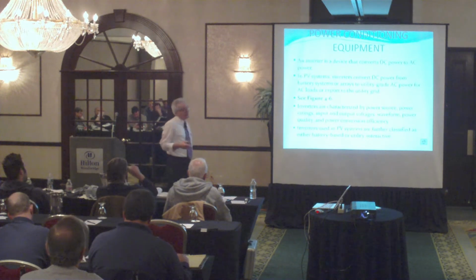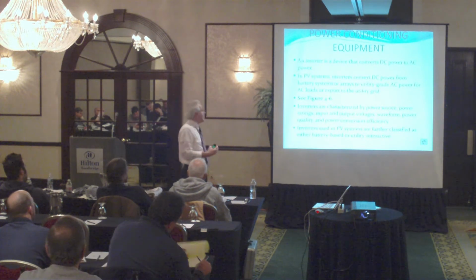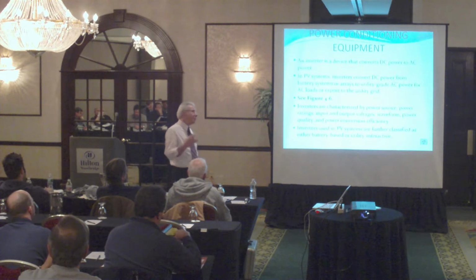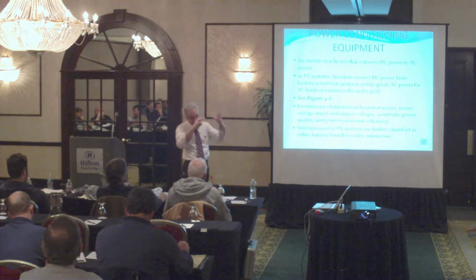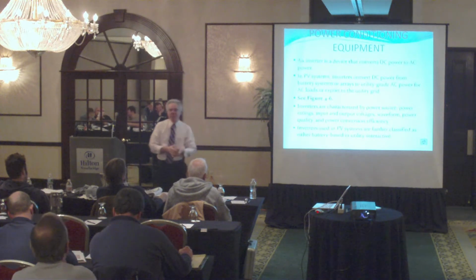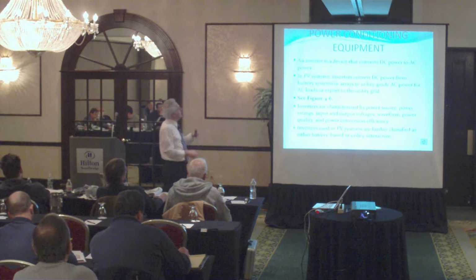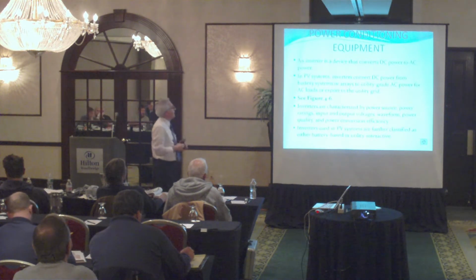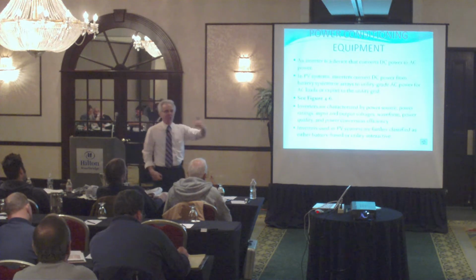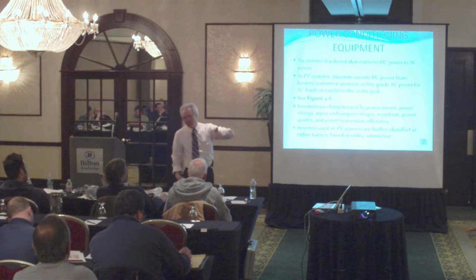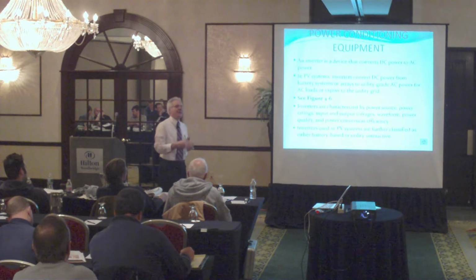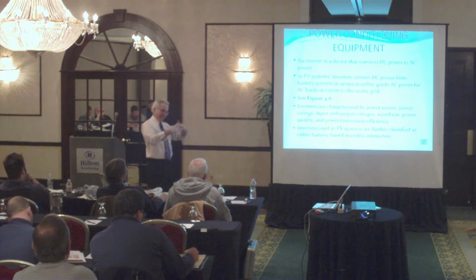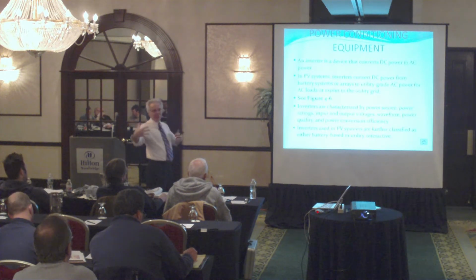Now, the other type of equipment you have in systems like that is, obviously, the power conditioning system. Sometimes you refer to the whole system as an inverter, because it has all these capabilities. Typically, an inverter changes DC to AC, and AC has to have voltage, current, as well as a frequency. It does all the cleanup to make sure that it matches the utility company's frequency, so it does a lot of the interfacing between the utility and the system.